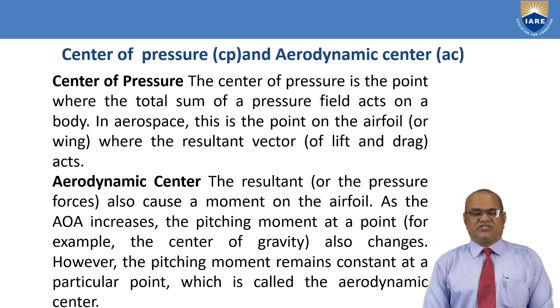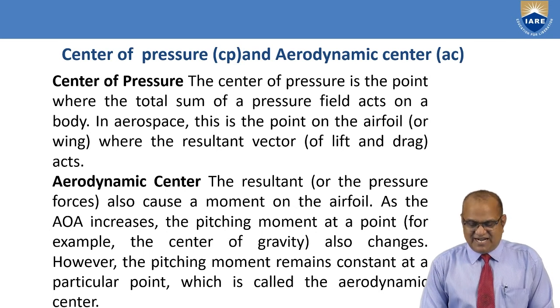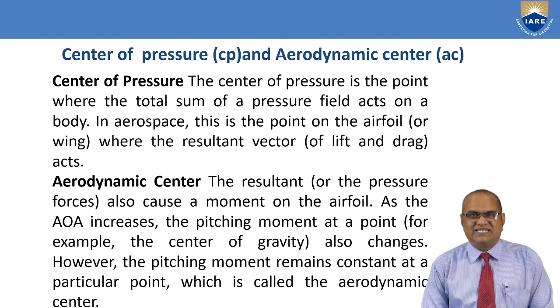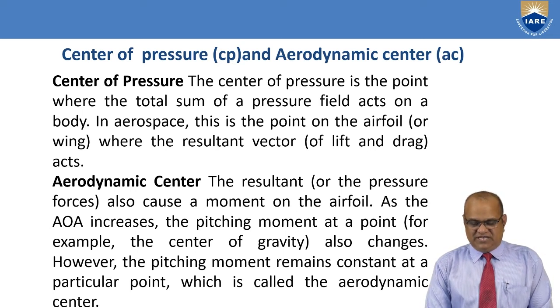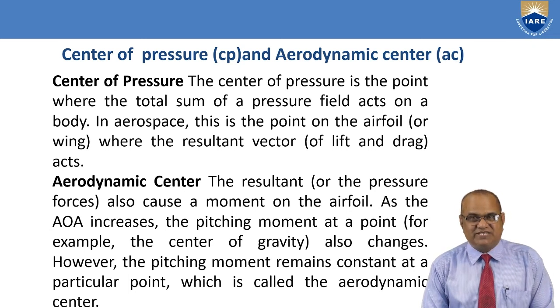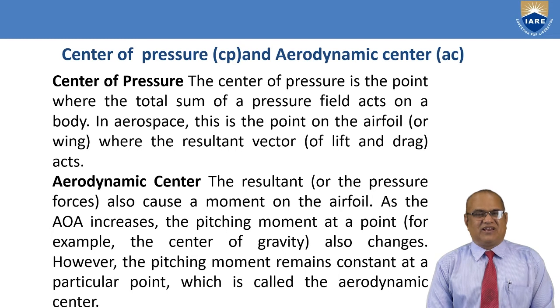The next point is the aerodynamic center. The resultant of the pressure forces also causes a moment on the airfoil. As the angle of attack increases, the pitching moment at a point, for example the center of gravity, also changes. However, the pitching moment remains constant at a particular point, which is called the aerodynamic center.